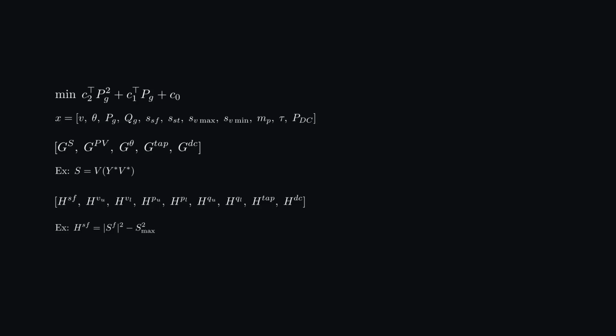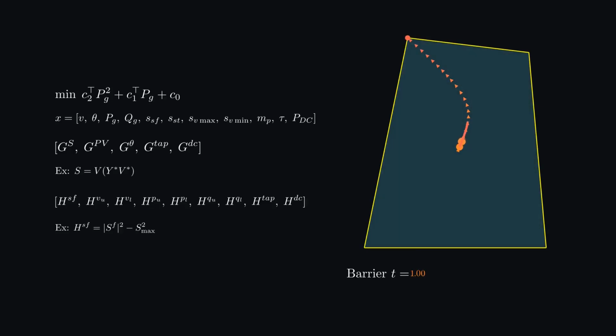In VeraGrid, the ACOPF is solved using a custom-built interior point method that handles the nonlinear equations and inequality constraints simultaneously. The algorithm searches for a feasible minimum cost solution within the full AC domain, enforcing voltage and power limits through barrier functions. In practice, the ACOPF is generally used to verify certain specific scenarios in both long-term and operational planning. Although it's computationally more intensive than the DCOPF, the ACOPF is progressively becoming more practical for routine studies thanks to advances in solver algorithms and the increasing availability of high-performance computing.